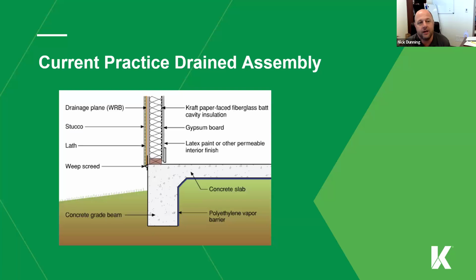But Hector nailed it on the head. I don't know how many times we find that things that are supposed to be open to drain, like weep screeds, are sealed shut. So now you just have a nice bit of water that's always built up there, and everything at the bottom is deteriorated, which I'm sure Mike loves when it's completely deteriorated where it's connecting to the slab. So, that's something to consider as well, that a lot of these things are just, for lack of a better term, dumb things that happen that cause a lot of damage that would have been really easily avoided. So we're not talking about avoiding a hurricane here. It's not putting too much mulch in.